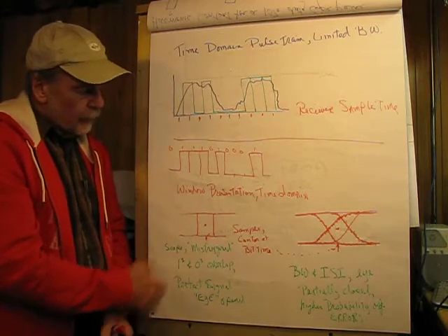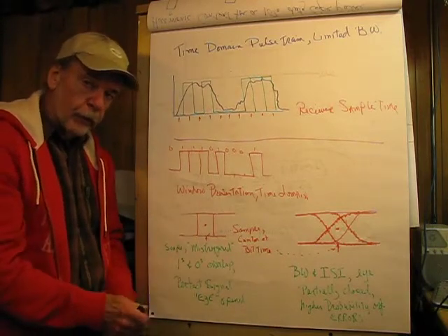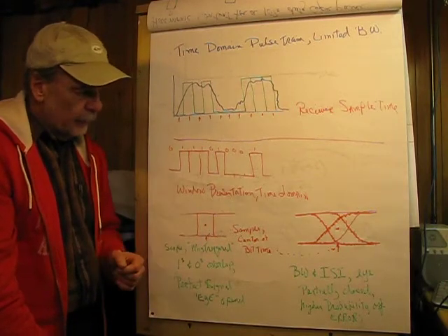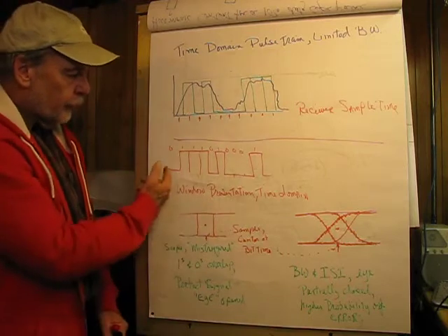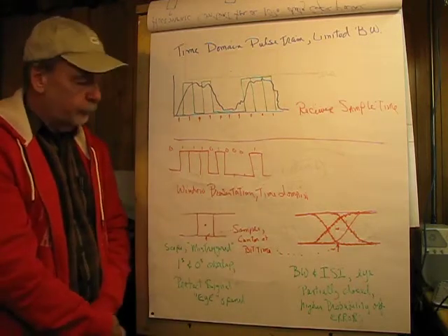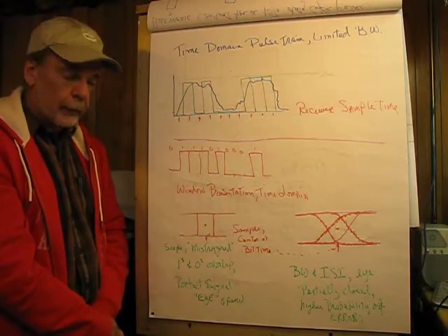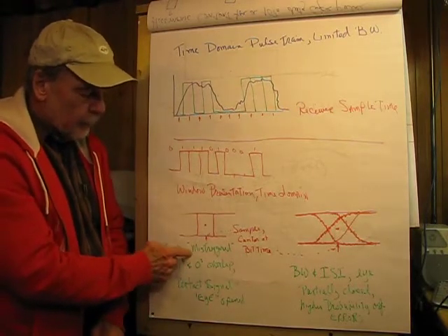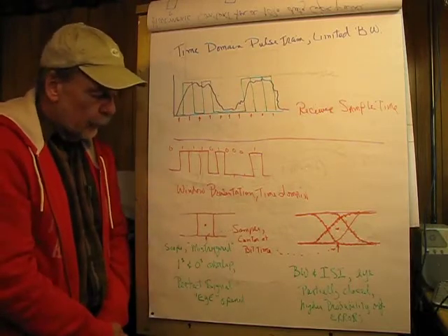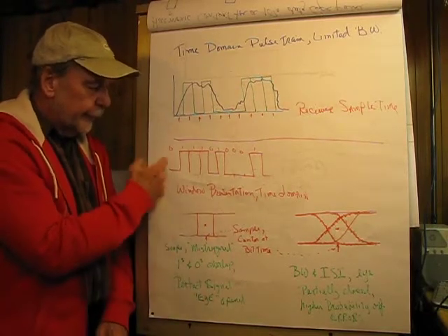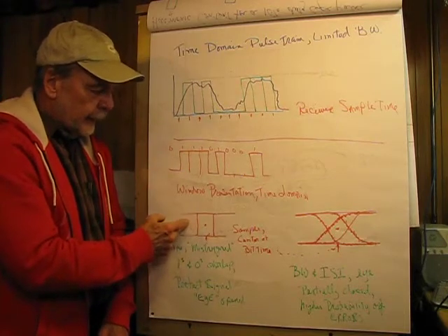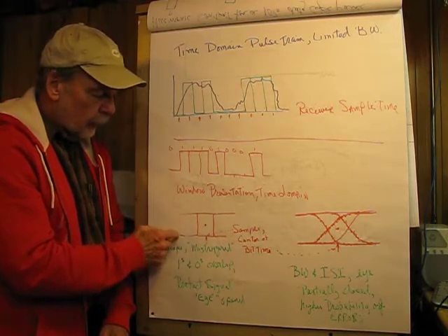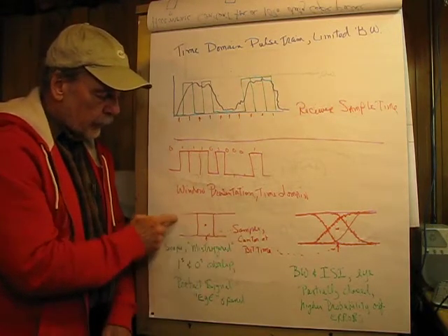So one of the ways we can use to take a look at pulses when they go through a transmission system, which is very popular, and this is in the time domain, is this waveform, and note that it's not a symmetrical 1-0 pattern. Now if we take our scope and analyze this and we mistrigger it, that simply means it's going to be triggering on, say, a 1, and you're going to get an overlay of 1s and 0s. So a 1 pulse might look like this, and a 0 might look like this.